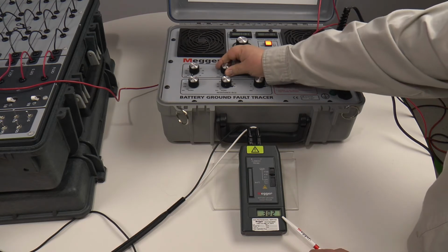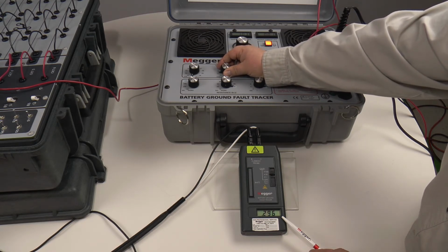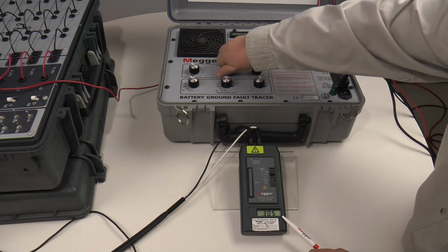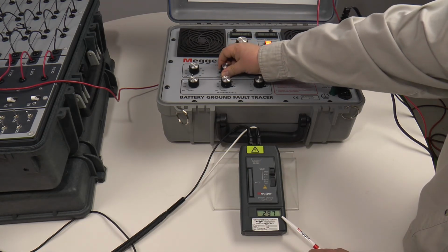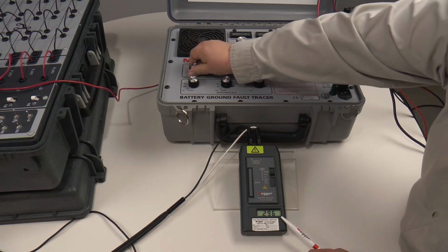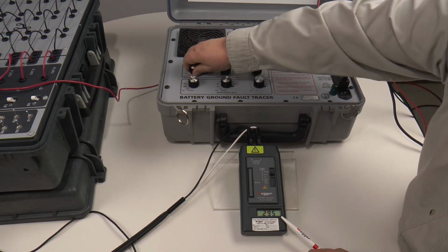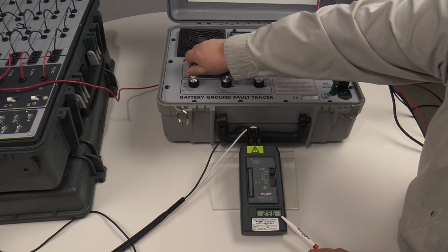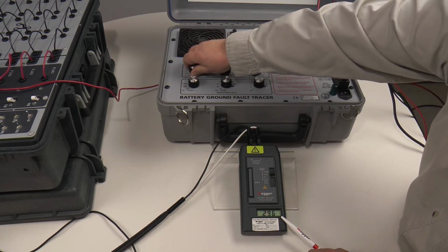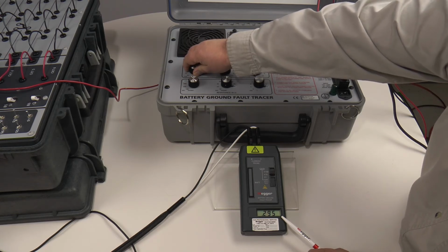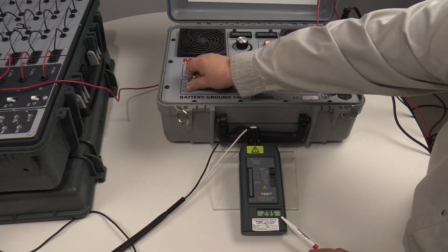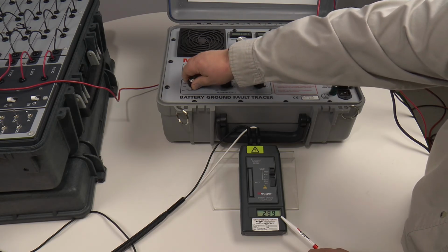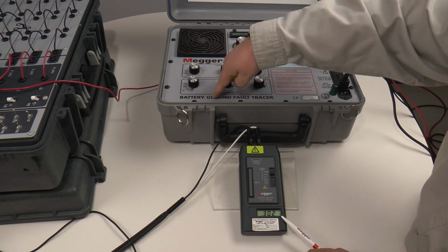In fact, if we keep going down through the capacitance dials, we can see the value just continues to go up. With the feedback loop in either direction, we are still adding capacitance. This is because there is no capacitance on the circuit to tune out. Now we go to the resistance knobs and notice the reading is going up. We have the feedback loop backwards, so we turn it around.